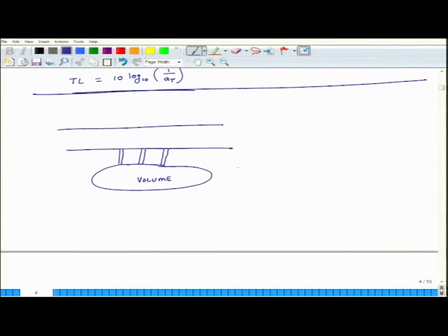In this case C A does not change because the volume of the muffler is the same. But if these pipes are equal in length, then acoustic mass is basically the acoustic mass associated with one pipe times the number of pipes, because the amount of air present in each pipe, we have to add those things.